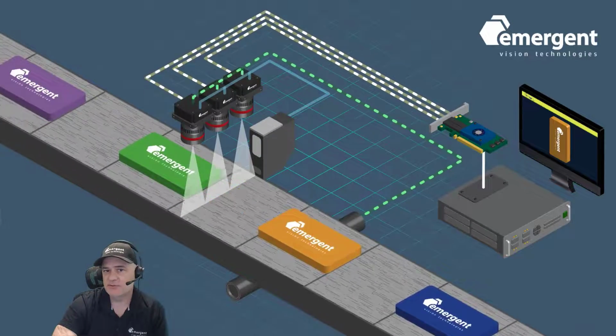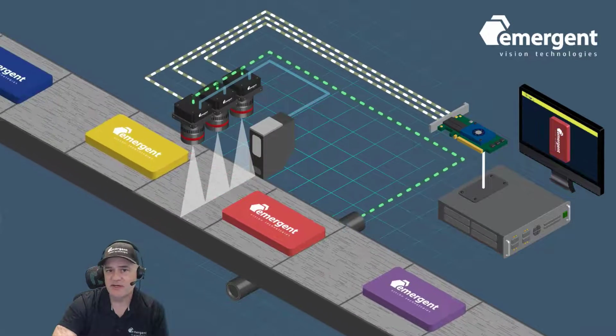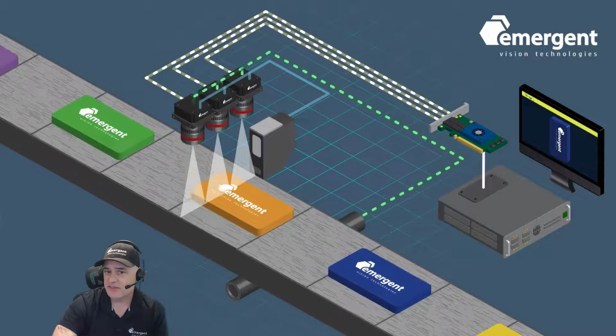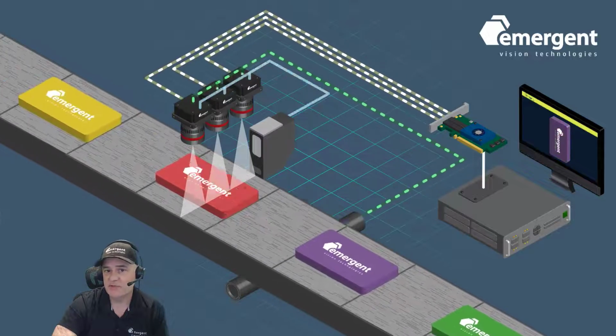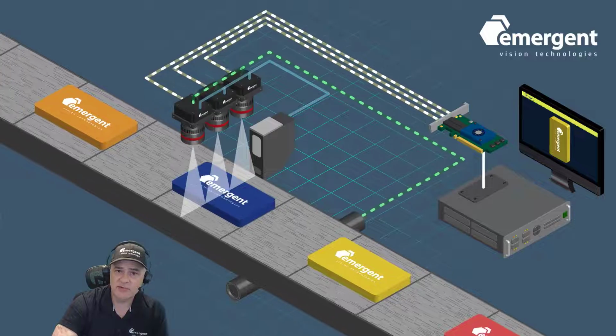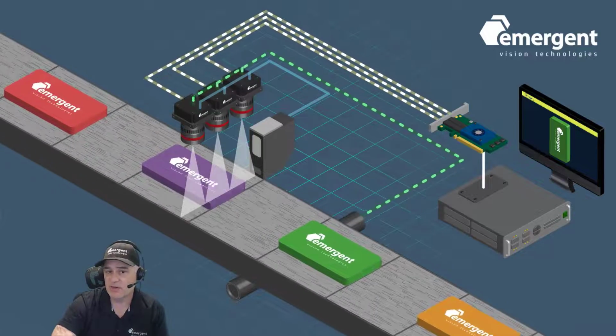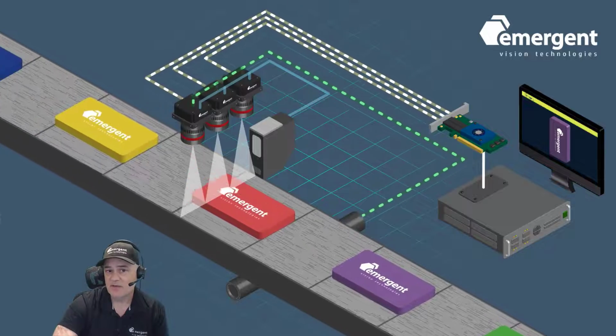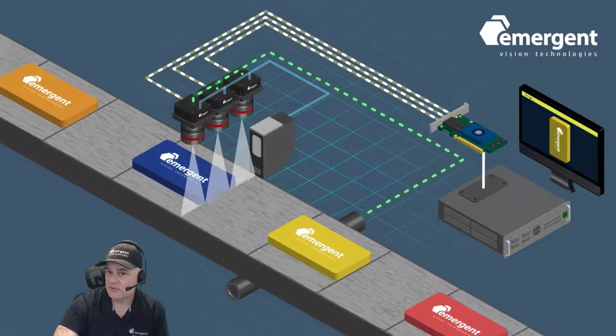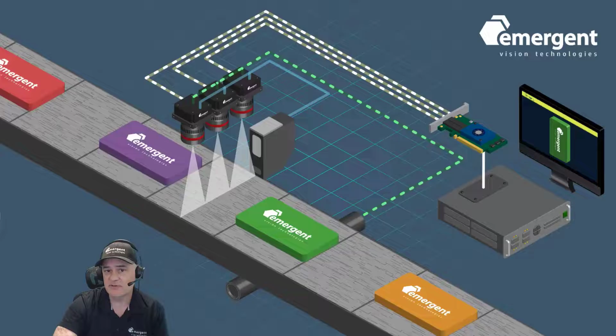This animation illustrates the same task with a line scan camera. Generally, line scan cameras are used for scanning a continuous web of material like print or fabric, but that does not preclude applications as shown here with discrete objects. The camera images here are hardware triggered by the sensor looking for objects on the conveyor.